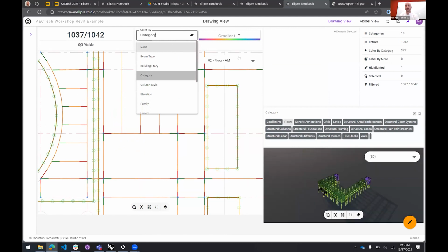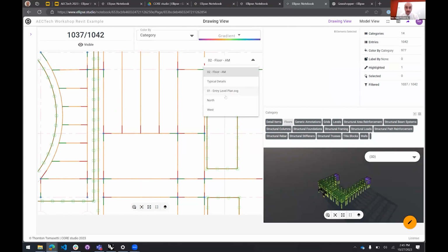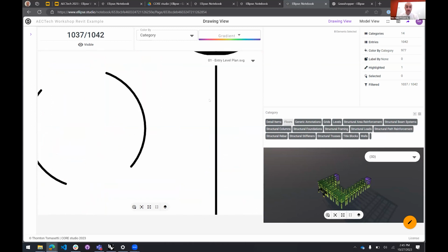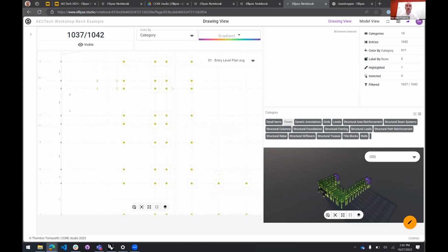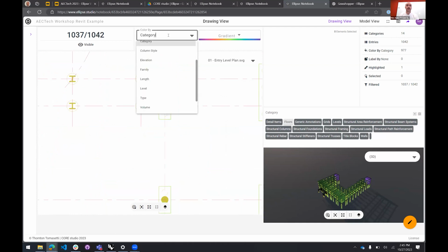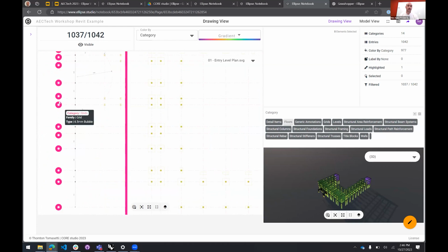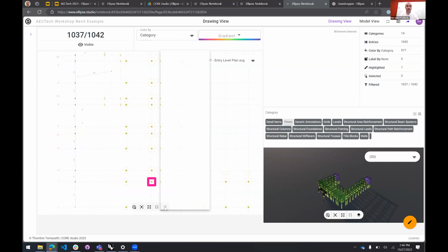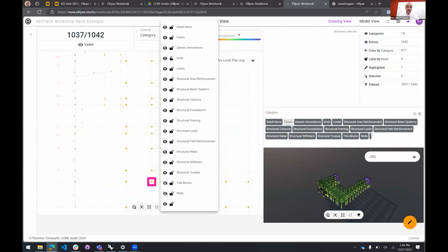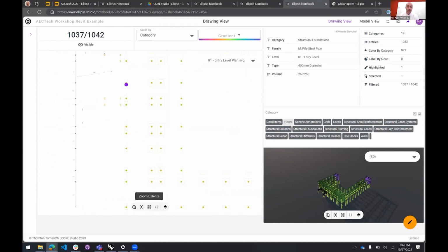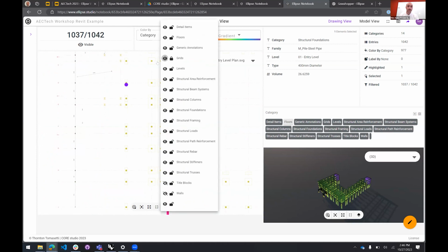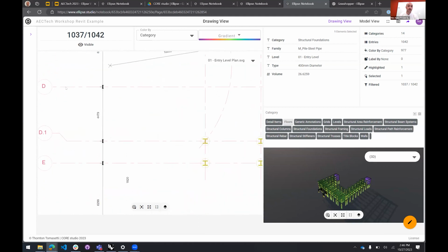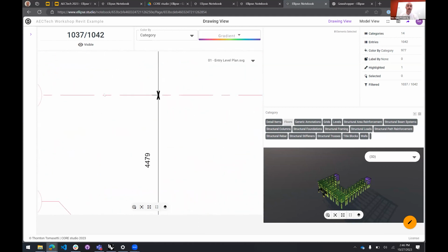view. If we switch to something that's not colored, like a floor plan, this can now be colored by category. And say you don't want the grid to be selected, or you don't want to see the grid, we could come in here and track down the grids and hide them or lock them. Well, not both. If we lock them and not hide them,